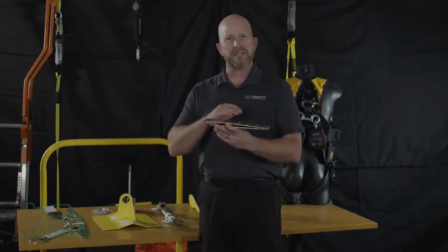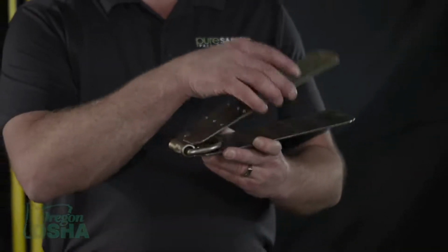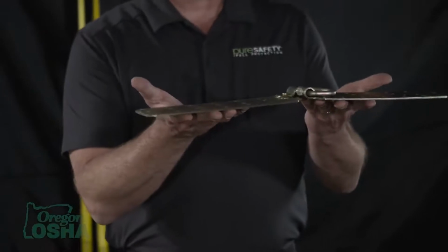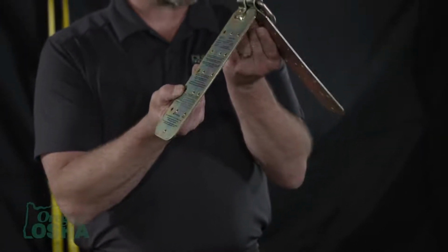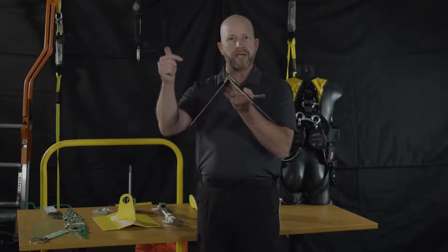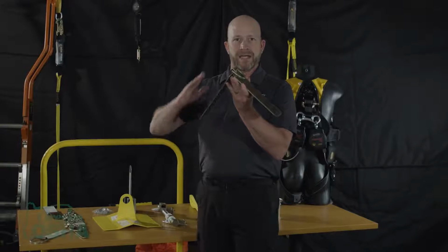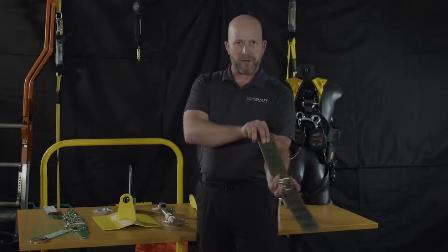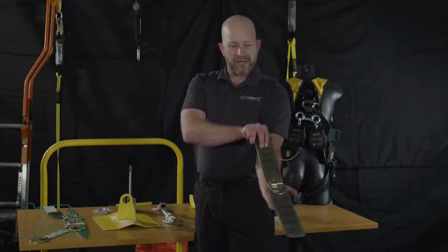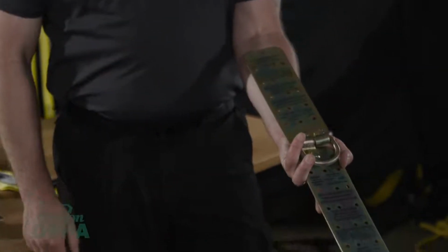So anchors like this, depending on the manufacturer and the design of the engineer, can be good all the way from a 0 in 12 all the way up to a 12-12 pitch, going through the substrate, going into the truss, and in some cases going in field, meaning that instead of being at the ridge, it will come down the eave along the rake or down towards the eave. And you will see there are a lot of holes in there.